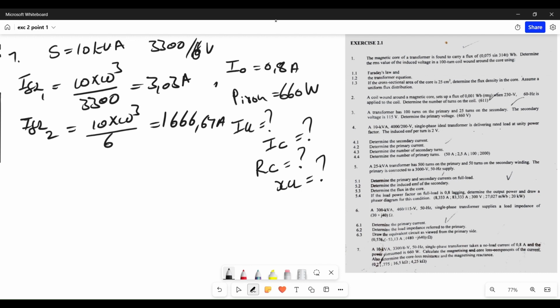So now I calculated the full load current on HV and on LV. The electrical machines rule says that whether I'm doing a short circuit test or an open circuit test, I have to check the percentage of the no load current on both sides and compare the two.